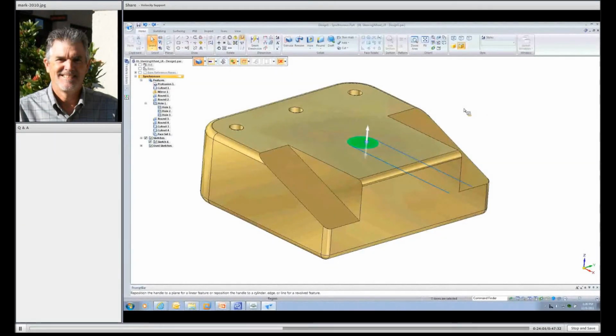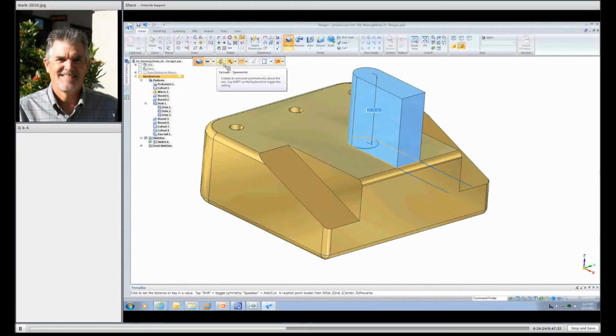And you notice now I can create a cutout anywhere in this model as far down as I want to go, and it creates that cutout for us very quickly. So regions, and we'll revisit regions in the next demonstration, but they're very powerful. The neat thing about regions is you notice I didn't have to trim any of the elements back. I could just simply pick the regions I wanted to work in and do the job that I needed to do, which I did very quickly there.